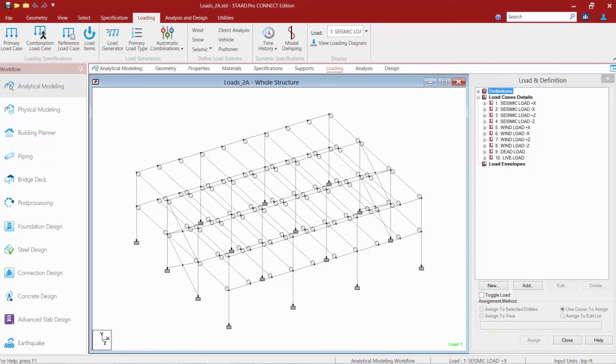We're now going to turn our attention back to our sample model. Now, just for clarity, I've gone ahead and removed all of the traditional load combinations that we had previously created, because now what we're going to do is create repeat style load cases instead, in preparation for possibly performing a P delta analysis on this model. So the first step is I'm going to show you how to create this repeat style load case manually, just like how we had done for the traditional load combinations.